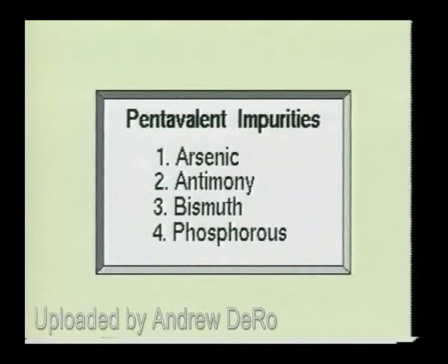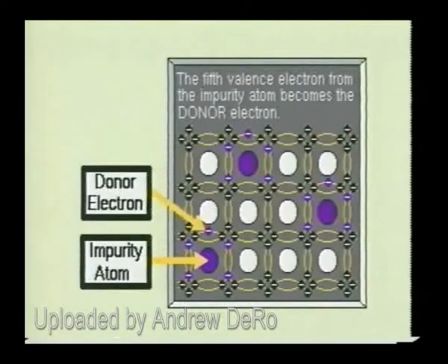When a pentavalent impurity is added to the intrinsic material, it causes an extra electron to be generated, because when the covalent bond forms the two elements together, there can be only 8 electrons in the valence shell. Since the pentavalent impurities have 5 electrons and the intrinsic materials have 4 electrons, when the two are combined, there is an extra free electron produced.